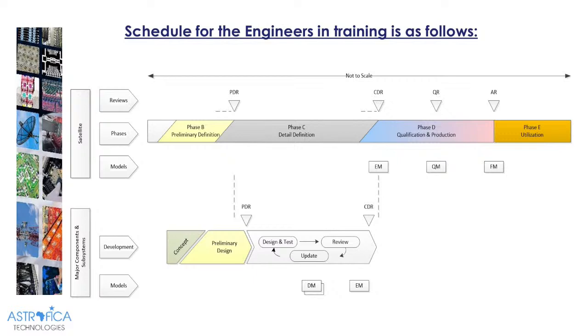And then we have the engineering model. We start then including our electronics in that, although we do not do any environmental tests on them, just functional tests, so that we understand that our design is actually performing the performance of the design. And then your qualification model, you then start doing your environmental test there.